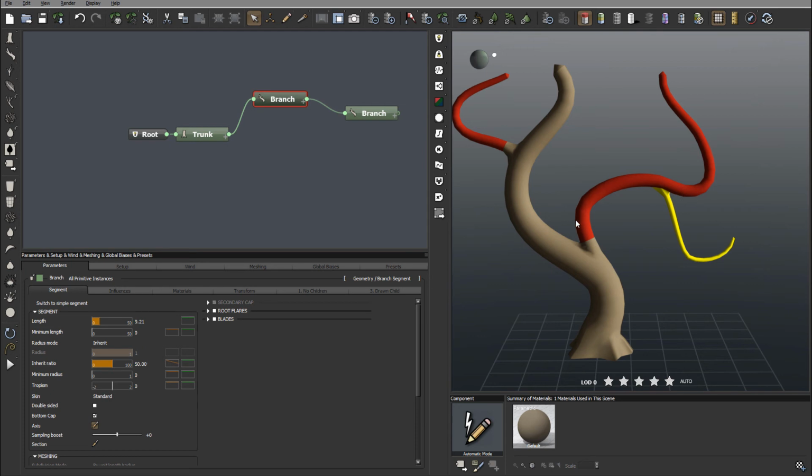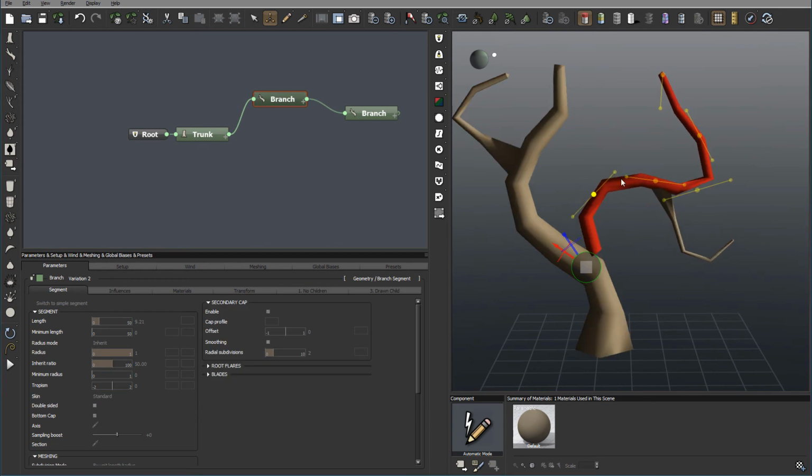As we draw, we're adding shape, and currently you can see this is a twisting shape. This is going with a spline, so we can actually preview it if we go to the touch up tool. You can again press Alt T, click on the icon, or go from the drop down. Notice right here we now have spline tools on the branches that we currently selected. With the spline tools we can modify them by moving the center point up and down. We can change angles as well, extend it, make it smooth, and also adjust it this way, pointing down for example.